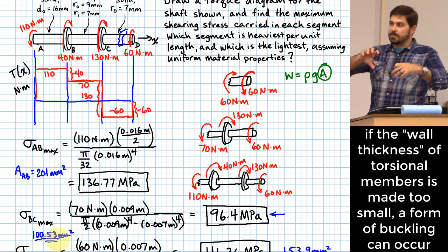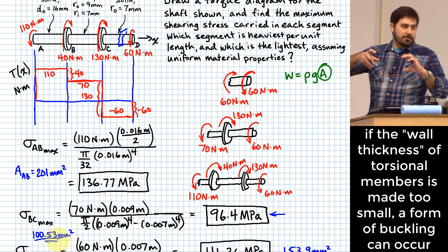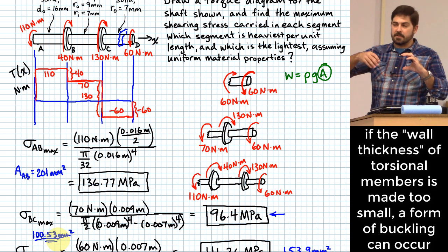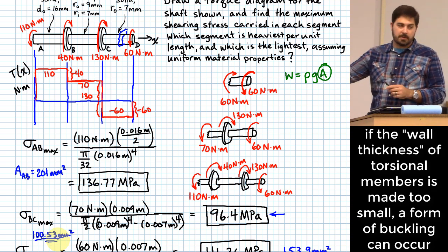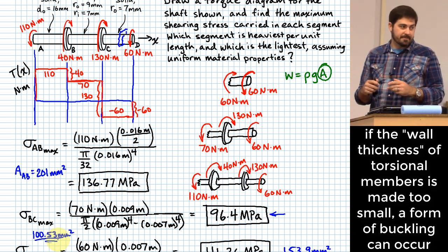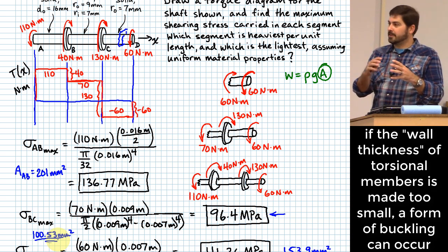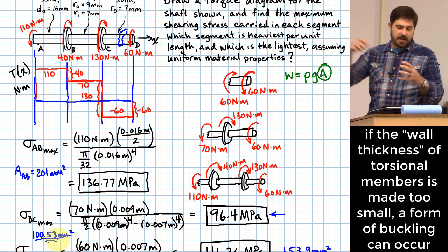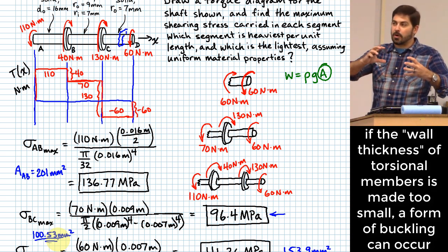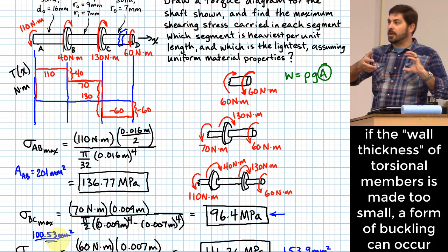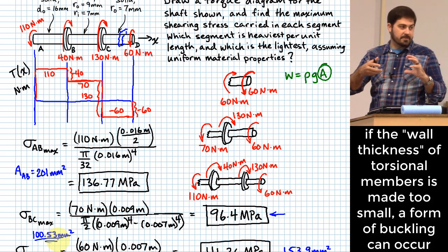So if you take an aluminum can and you start to twist it, another effect actually takes over, and it's an effect that's very similar to the buckling that we saw with respect to columns, right? The material itself doesn't actually stay planar like we expect it to in our derivation here, so it tends to start crumpling as you turn it before it actually yields the material.